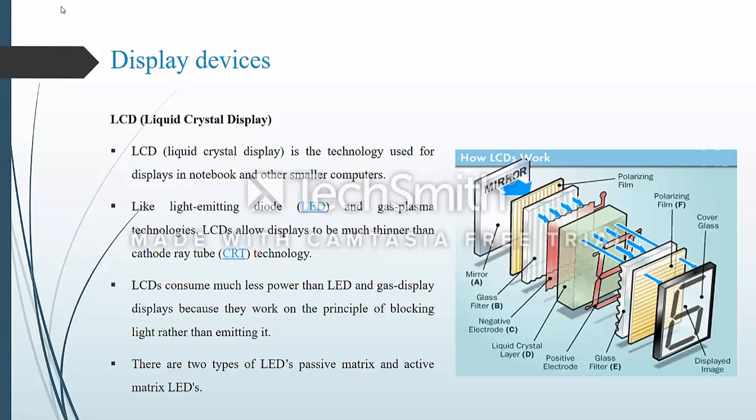As light strikes the first filter, it is polarized. The molecules in each layer then guide the light they receive to the next layer. As the light passes through the liquid crystal layers, the molecules also change the light's plane of vibration to match their own angle.